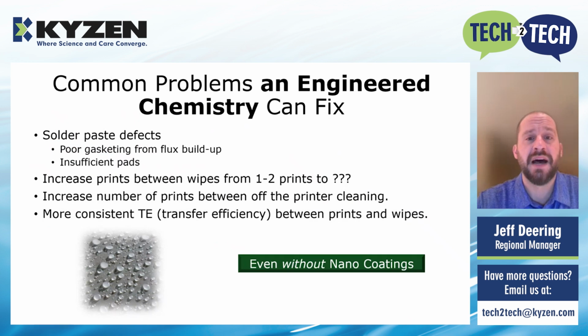Next, I'd like to talk about the common problems an engineered chemistry can fix. First and foremost, some common solder paste defects: poor gasketing from flux buildup and insufficient pads. Engineered chemistry can help increase your prints between wipes from 1 to 2 to however many we can determine when we work to optimize your process. It also increases the number of prints between off the printer cleaning. And most importantly, engineered chemistry provides a more consistent transfer efficiency between prints and wipes. All of this, even without nano coatings on your stencils.